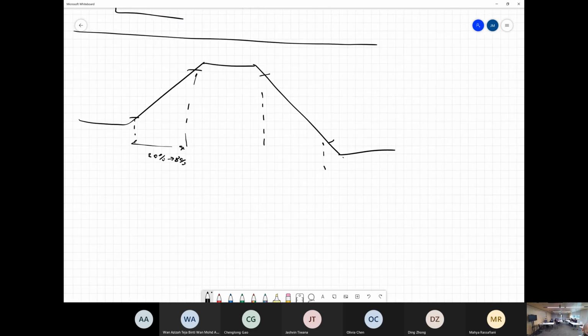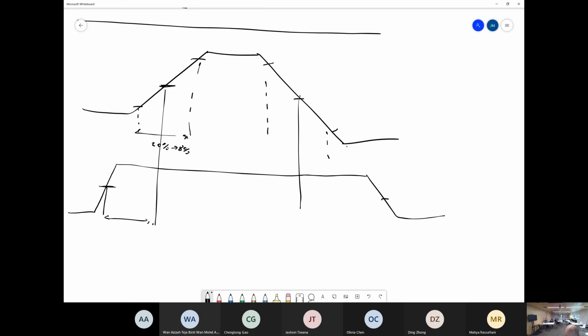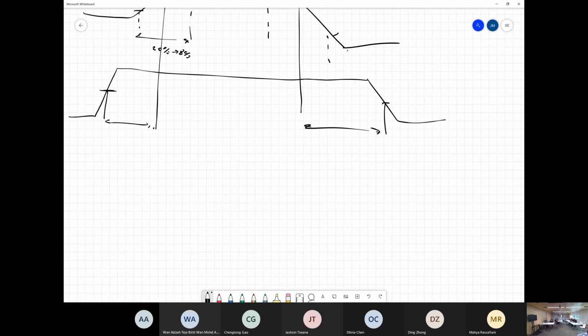You'll also have propagation delay. Say, for example, the 50% mark from here to the 50% mark on here. This delta of time here, that's your propagation delay. Similarly, 50%, 50%, from here to here, that's your propagation delay there, right? So those are the 4 measurements you need: rise time and propagation delay for the falling and rising edges. They're important as well.